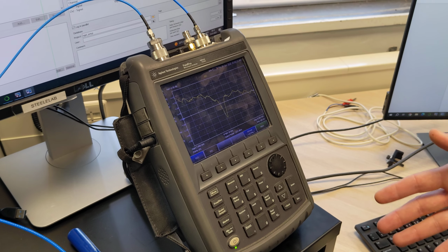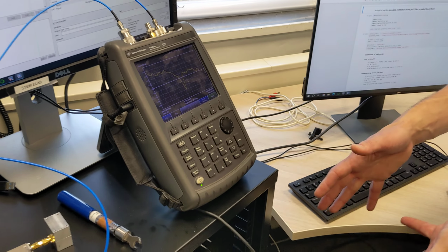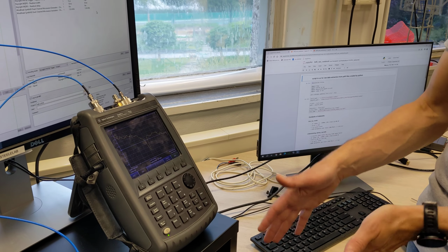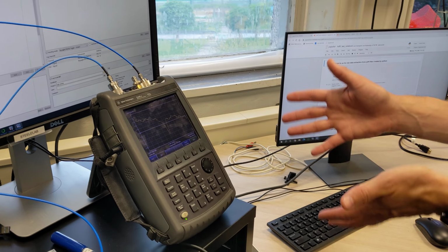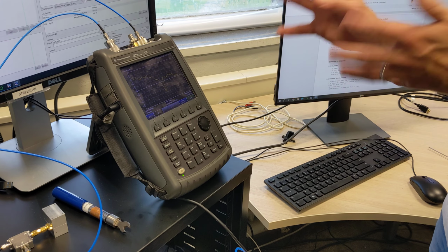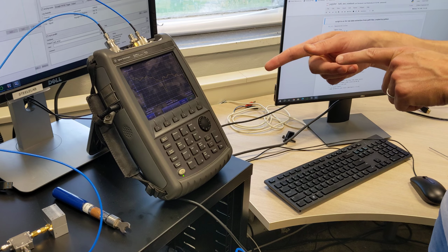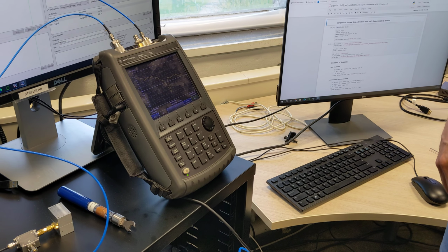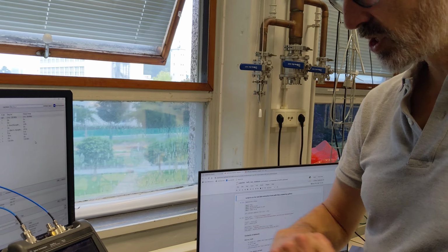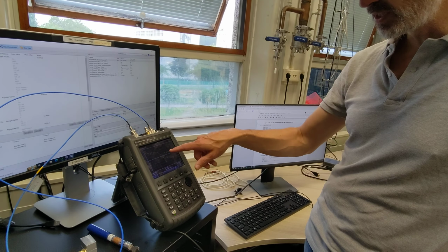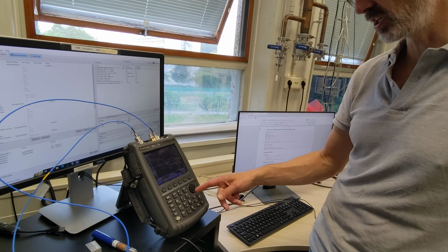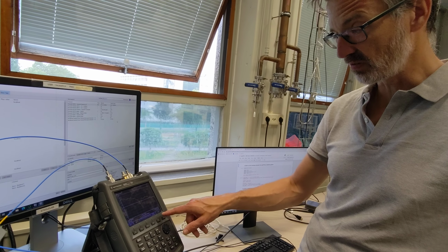Now, our aim is to replicate this measurement with time domain hardware. But time domain hardware does not measure magnitude, it does not measure phase, it measures quadratures. So we want to set this up to measure quadratures. But before we do that, I also want to advertise that this is an overcoupled cavity, which means the dip in magnitude is very small. But it's overcoupled, so there should be a huge signal about the presence of the cavity.